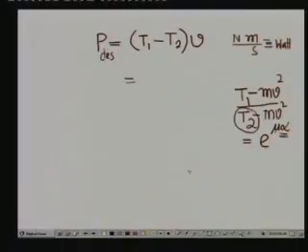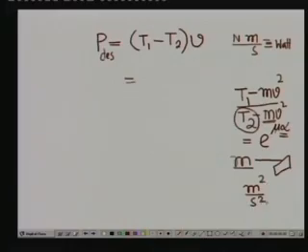Okay. Now, what is happening? I think I have mentioned about this m. See, this m is basically the mass of the belt material per unit length per unit cross section. So, if we look into this particular equation, what is V square? V square, we know, will come out to be meter square per second square.